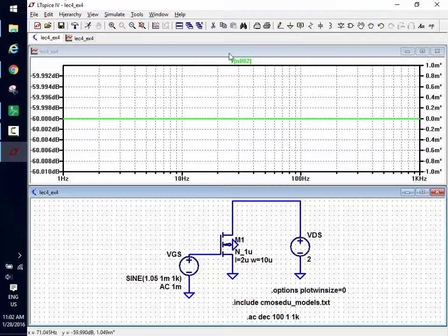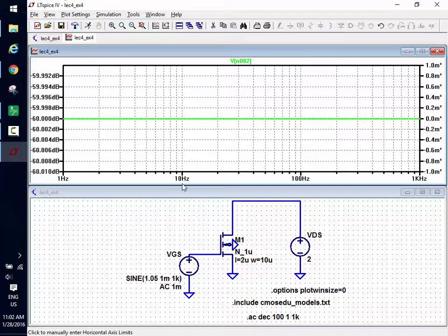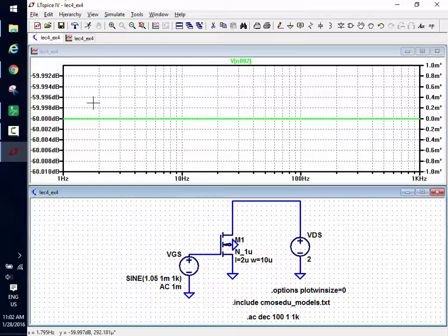Yes? Okay, for small signal, I can sweep the frequency and look at what the response looks like. So I could say, hey, at 1 kilohertz, the gain is 5, and at 10 kilohertz, it's 1. If I do transient, small signal assumes signals are small. So if I put in bigger signals, I'm not going to see any distortion from moving down the curve. Like if I'm doing an audio amp, which is what the project was last time, if I have bigger signals and I do a small signal analysis, it's just going to say perfect behavior. So I have to use a transient to look at the behavior for distortion in larger signals.